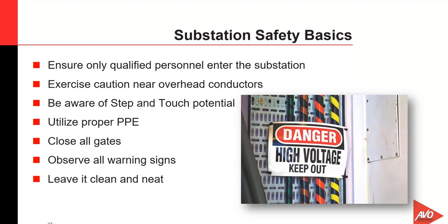Operating any type of machinery is important. Whenever we're doing testing inside a substation, we could be using ladders inside the substation. So make sure that we don't come in contact with them. Don't get in line, or maintain our boundaries within those substations as well. Be aware of step and touch potential. That's an important one. We want to make sure that we test our connections inside of that substation and make sure that all of our connections are good, solid connections. Make sure none of them are broken. That's going to mitigate any type of touch potential that we could incur inside of our substation.